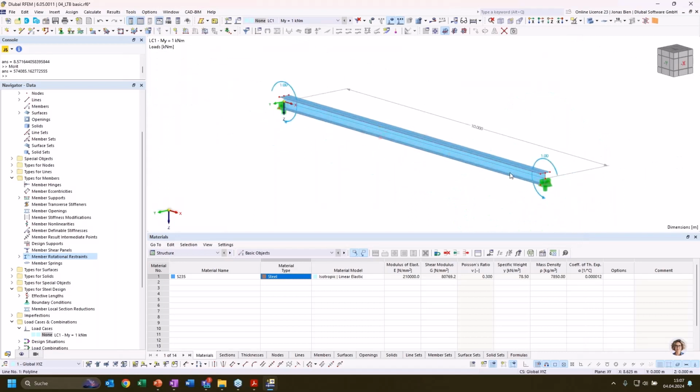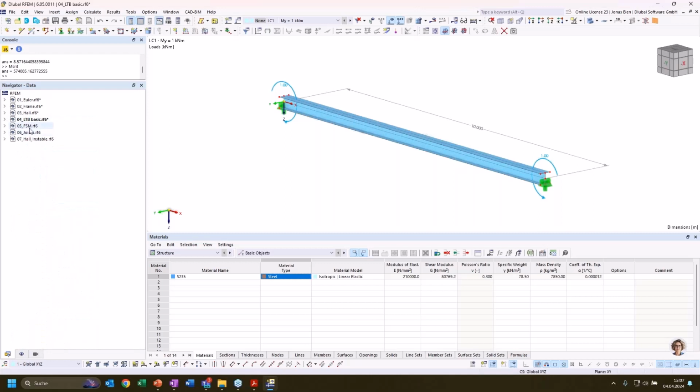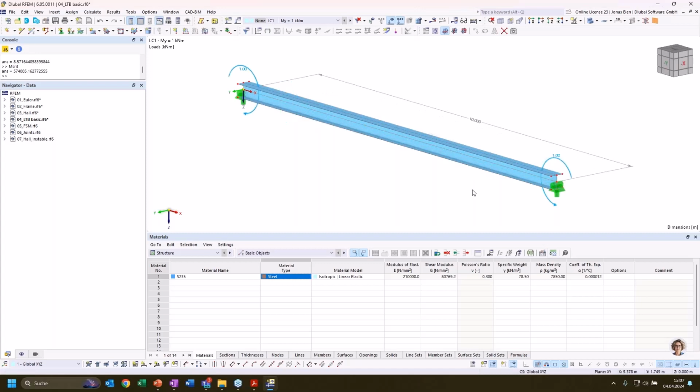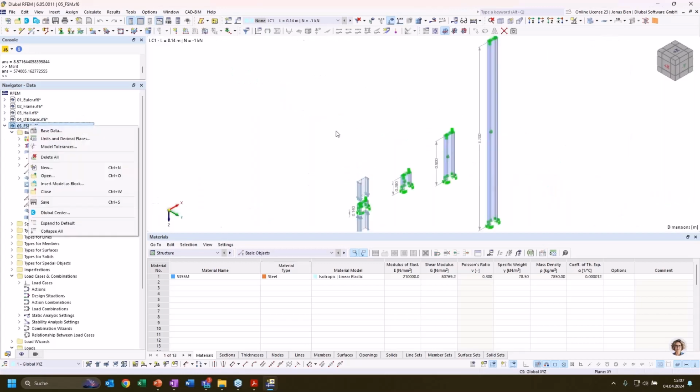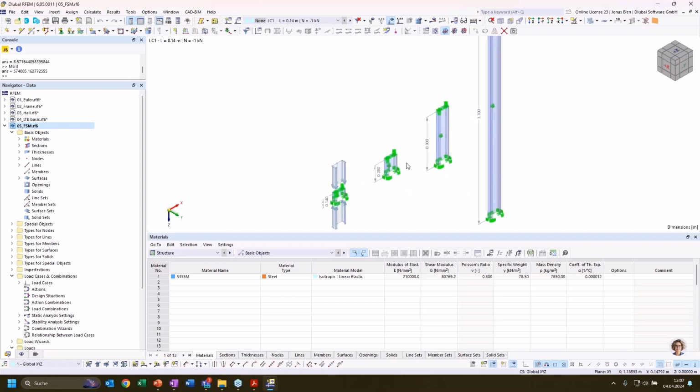And now we could mesh this in a very fine sense to do stability analysis for this shell model. By doing so, we could also analyze local buckling modes of the section. Because it's not very interesting to do it with a hot rolled section that is in this case not susceptible to those local failure modes, I want to do it with a cold formed thin walled section.